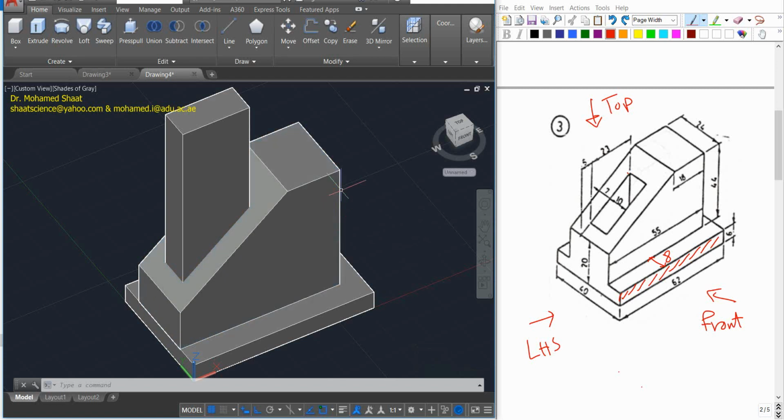It is a long trip. There is a more advanced approach that is used in SolidWorks, for example, but this is how it works in AutoCAD. We have to build a 3D solid for the opening first, making sure that this 3D solid of the opening intersects with the shape. Then you're gonna subtract one from the other. I need to subtract this thing from this part, okay?